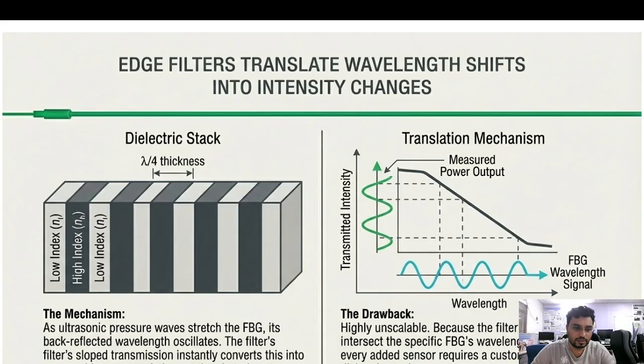Now we are going to discuss how edge filters translate wavelength shifts into intensity changes. You know we have already discussed the dielectric stack, which has lambda by 4 thickness layers with alternating refractive index, high, low, high.